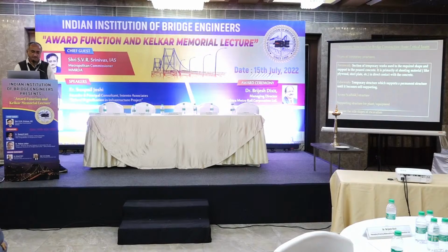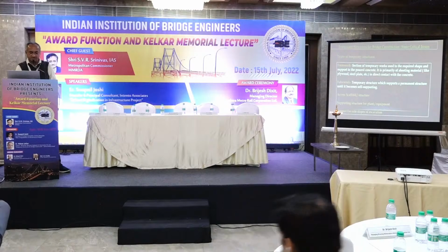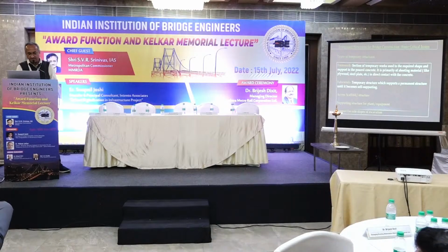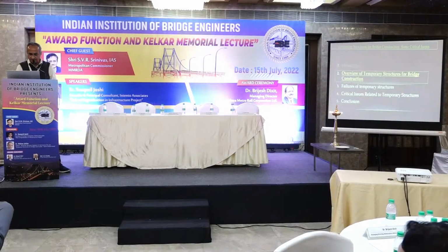There is basically terminology associated with temporary structures. Formwork is immediately in contact with fresh concrete, and gives it the shape which is desired as per design. Falsework is probably the most critical item of all these, which supports the permanent structure till it becomes self-supporting. Then there are access scaffolds, supporting structures for plant, and then supporting structures for the sides of the excavation.